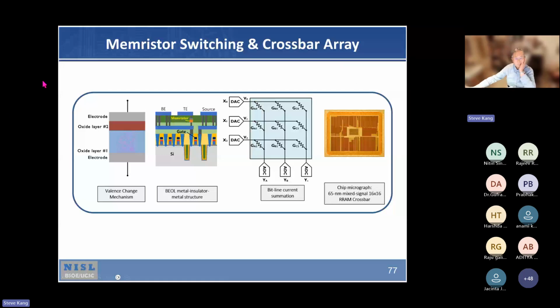But what is exciting is the following. In the HP memristor, they have a top electrode and a bottom electrode, and then an oxide layer, doped and undoped. On the left-hand side, this doping is happening. Fully doped, so conduction happens. Now, if you apply this voltage negatively, then it dissolves, so resistance becomes high.